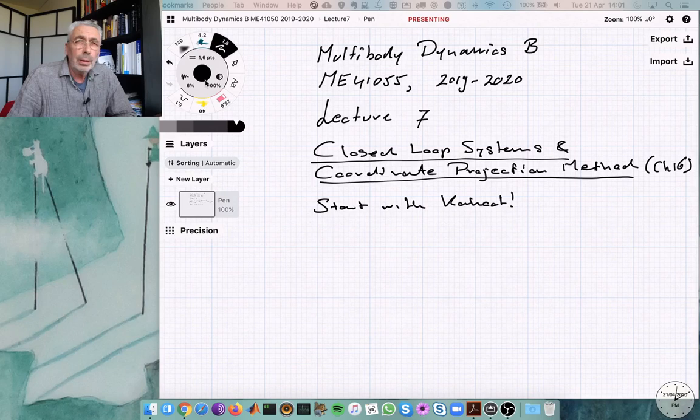That was with Lagrange equations, where we went up to the level of energy and went down to the equation of motion. The other method was the TMT method, which stayed on the level of force equals mass times acceleration. But the core of this method is that you have to express the coordinates in terms of your generalized coordinates.